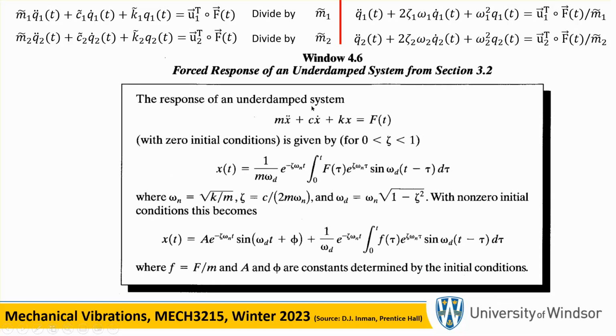Now for stuff like this, we have the solution. Notice that these equations are forced damped response equations, and we have a solution for them. If you ever have something like this from back in week 4, 5, we can write the solution in terms of the impulse response function and the convolution. Remember the convolution, this is the Duhamel integral, the convolution integral. And if there are initial conditions, of course you have to throw them in right there. This is the Duhamel integral.